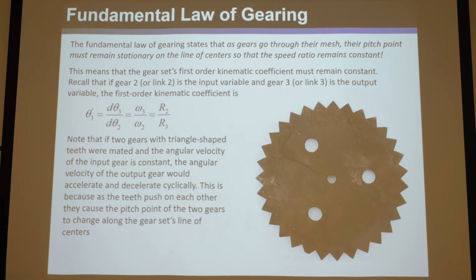In the very logo of their company, they're demonstrating they have no idea how mechanical things work, because pretty much every shape I've ever seen an artist do would violate the fundamental law of gearing. Even though it would convert an angular velocity to some output, that output is going to fluctuate in speed instead of maintaining the nice constant speed that gears are intended to deliver.